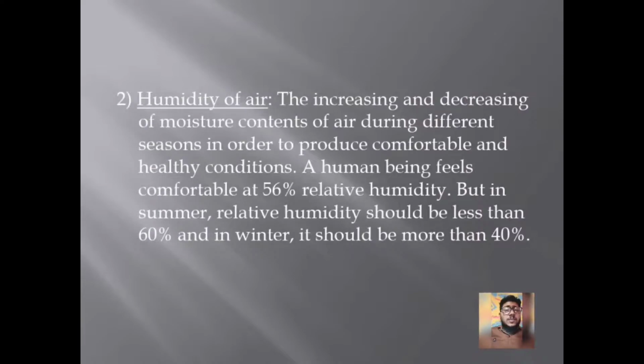Relative humidity between 40% and 70% does not have a major impact on thermal comfort. In workplaces which are not air conditioned or where the weather conditions outdoors may influence the indoor thermal environment, relative humidity may be higher than 70%. Humidity in the outdoor environment can vary greatly and may be dependent on whether there are drying processes where steam is given off.